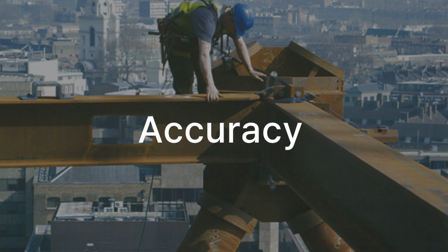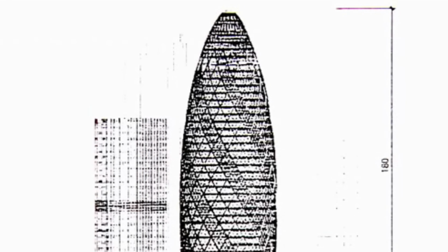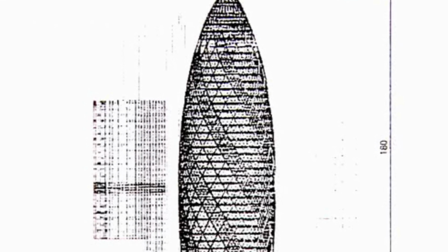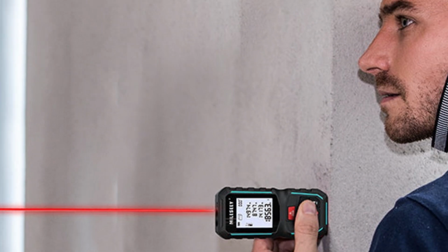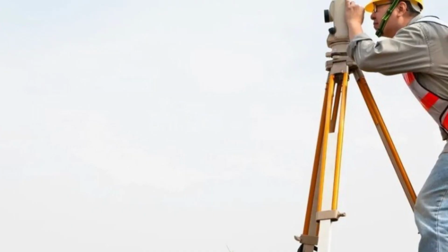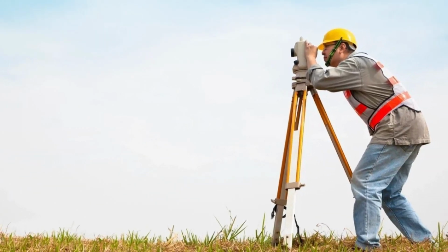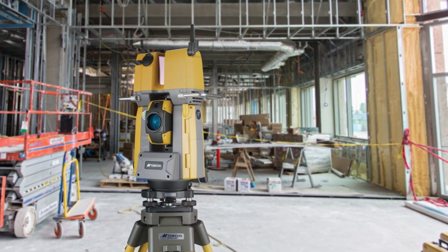Here's the important part. First, they establish a baseline and reference points, and accurately mark the installation position of each component. They mobilize equipment, like laser distance meters or a total station, to align the horizontality, verticality, and height to the millimeter level.